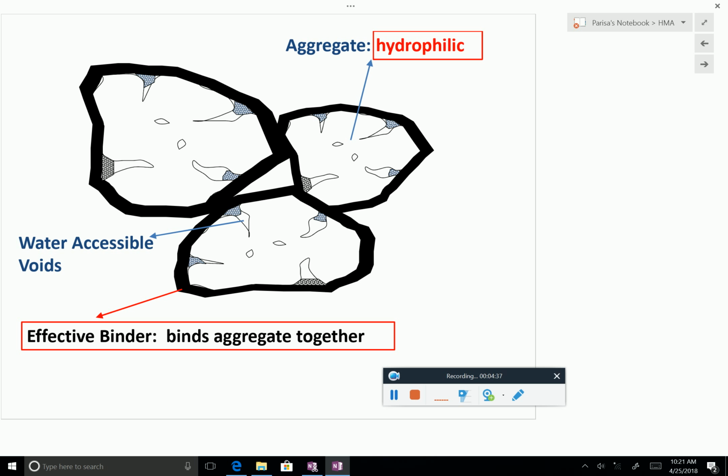So now, just before going to the process, let's remember the structure of asphalt aggregates. You have absorbed binder, which is in the pores, and then you have the effective binder, which is actually the glue that holds everything together. If you have too much of that, the material deforms too easily. If you have too little, you don't have enough glue, and it's not stable enough.